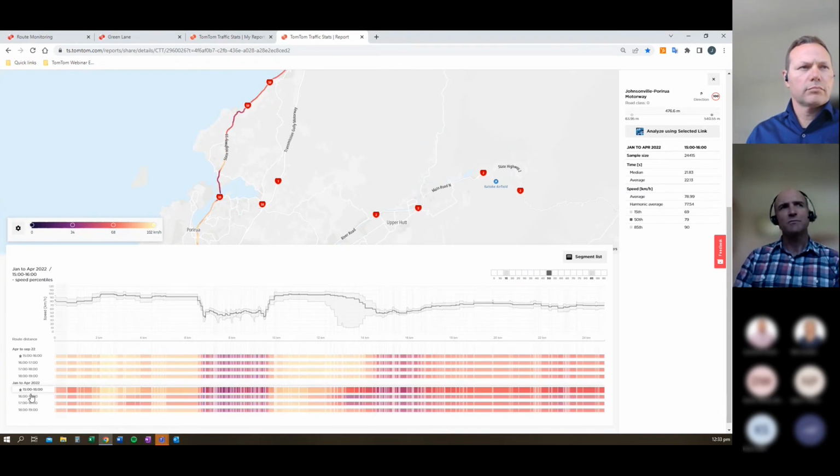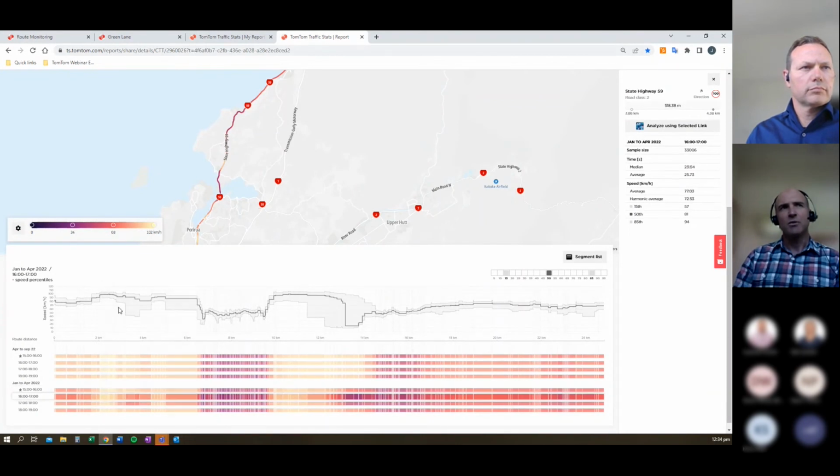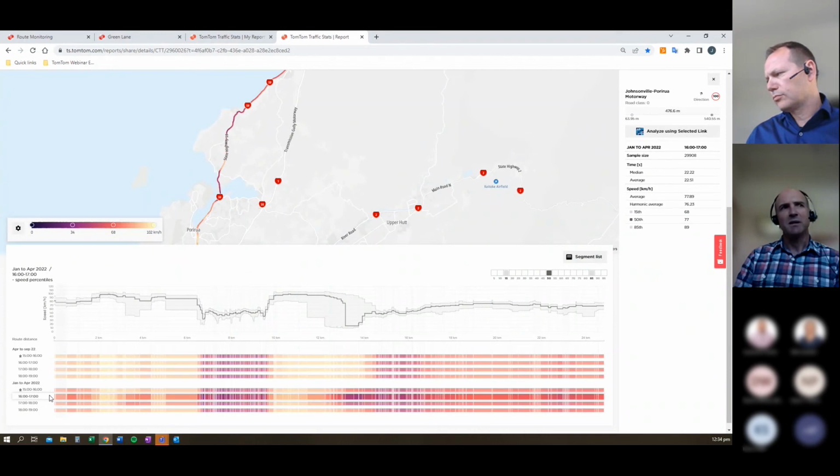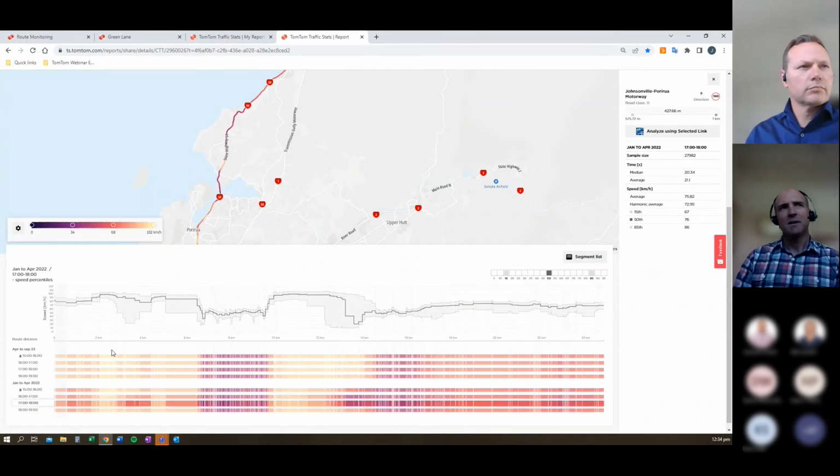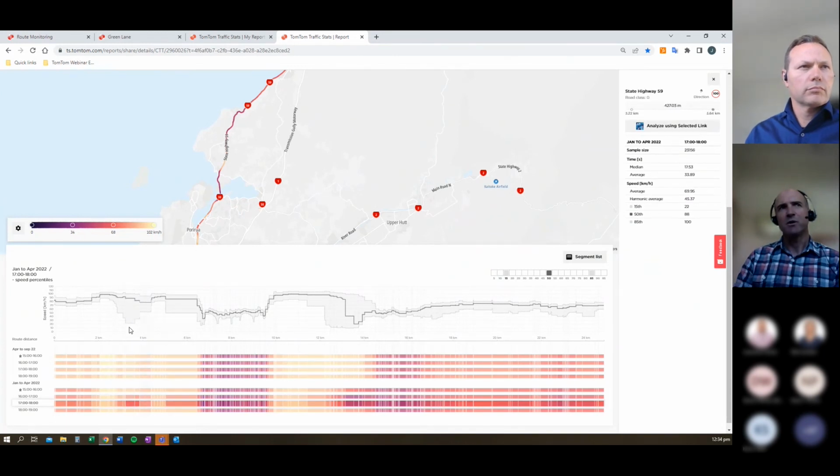From 3 to 4, again, quite a big change in terms of where that speed profile changes, but also back in this section as we travel past Porirua before we hit Mana. Again, another peak, another drop through here. Here are the traffic lights, and the on-ramp from Porirua. And then again, much greater variability through the profile.